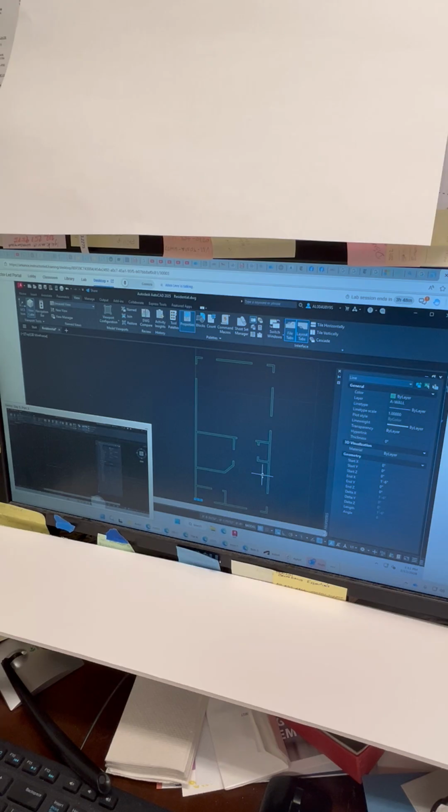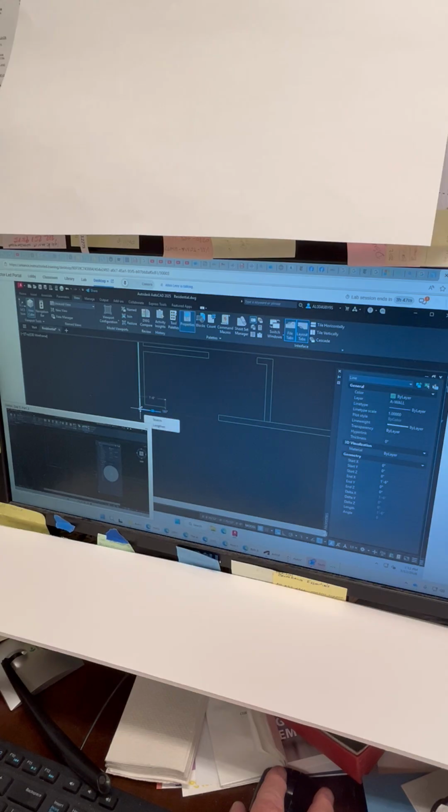And by the way, you can actually see this if you look down at your coordinates. I never mentioned these, I told you to turn it on, but I never referenced it. These coordinates down here, look at this. You hover over this one, and it says it's 0, 0. Now, it's going to change if I move my cursor down there, of course. But this is 0, 0. And if I hover over this one, it is 1'6" in the x, 0 in the y. And we can see that right there.